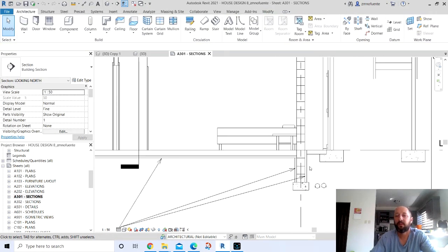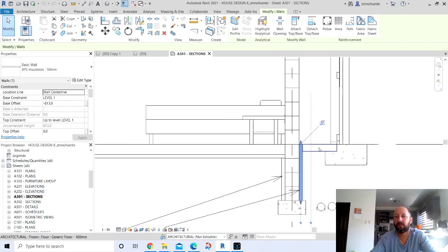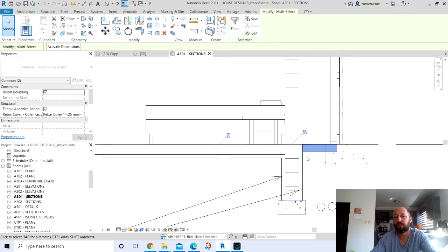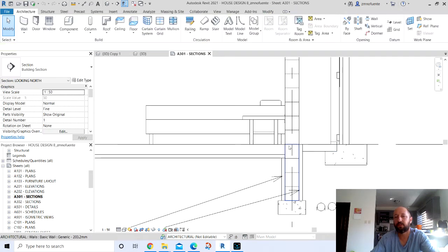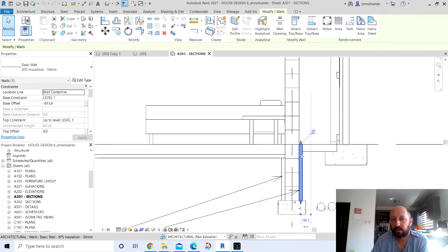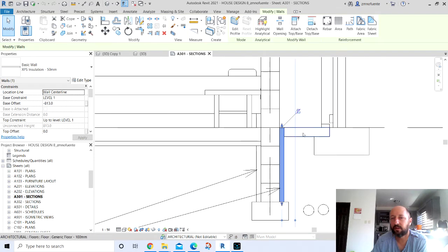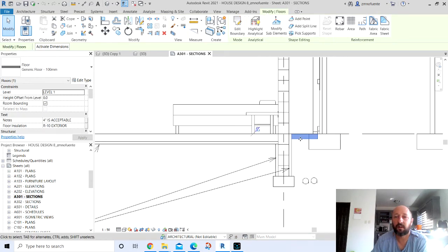Anyways, so if you insulate here, you want to decrease thermal bridging. So concrete is a good conductor of thermal energy. So you don't want to have any openings to the exterior that are not insulated, or you don't want to have any thermal bridging. So you want to have insulation fully encapsulating your entire structure. So here I decided to run the insulation up to the floor level, and then you have an exterior slab. Really, it's just to hold the insulation in your exterior wall.